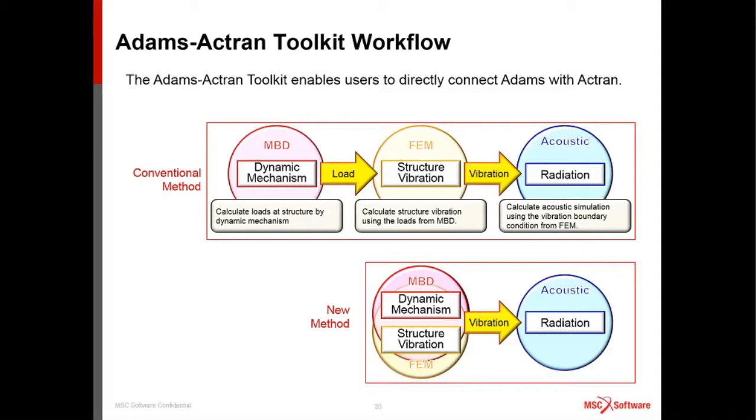So here, let's take a look at the conventional method, how people usually perform this type of simulation with a moving mechanism. First, they would use an MBD software to generate the dynamic loading. Then they will use some sort of FEA software to convert the dynamic loading results from the MBD software into the OP2 surface response result file, which is readable by the acoustic software. So in the conventional method, which is still prevailing, you can see we are leveraging 3 different interfaces in this